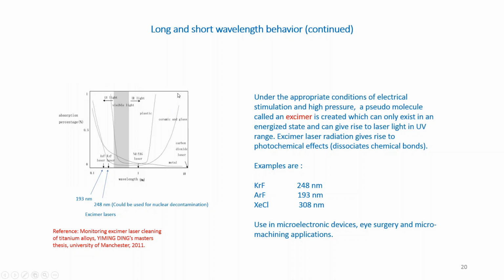So if you're only dealing with removing plastic, it's better to use near mid IR. For excimer lasers, the absence of thermal effects and removal of material by photoablation or dissociation of molecules is a big advantage.